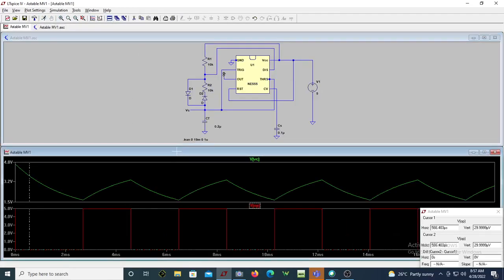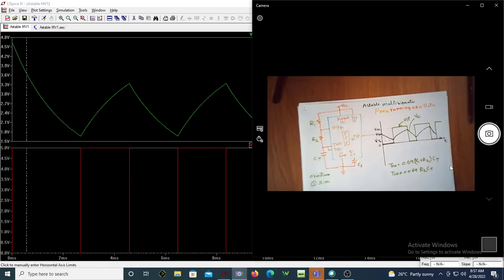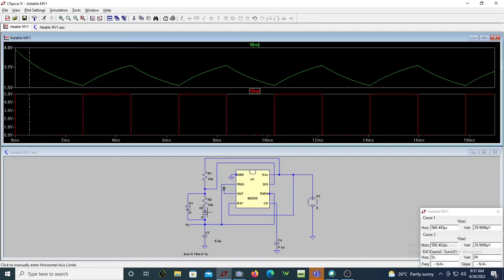Can you see there it's almost looking 50%. Of course you can certainly measure while doing the simulation. This on time is almost equal to off time. So what we have made in this expression here is, this is R1 plus RF, this is R2 plus RF, because R2 plus RF is resulting from this diode. R1 plus RF is during this diode. This is how you are able to make exactly 50% duty cycle using two resistors of the same value, even in a practical case.